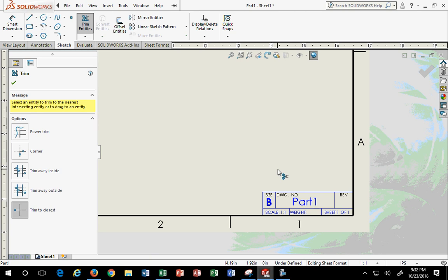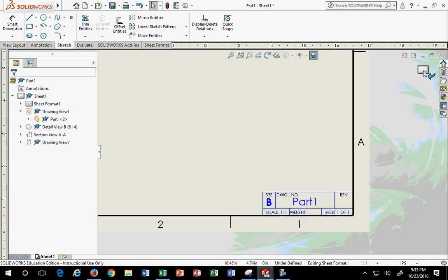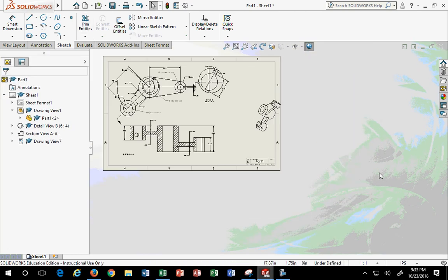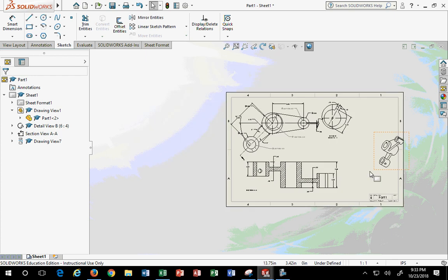And then I'm looking at the printed drawing saying, I can't see any of these dimensions, because if I print a C size on an 8.5 by 11 sheet of paper, all of the dimension heights, everything is correlated to printing on a C size sheet of paper, not on an A size. So everything is miniaturized and you can't see anything. So I've had students suffer through the opposite. If you can plan it out a little better, then you won't have the issue to begin with.